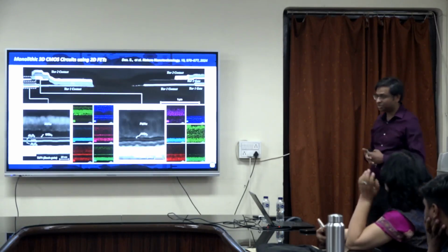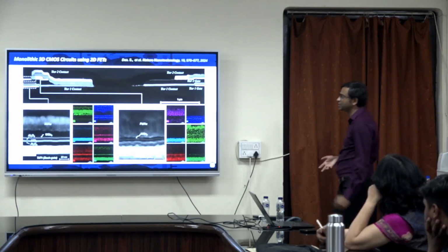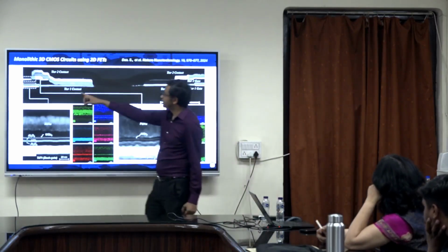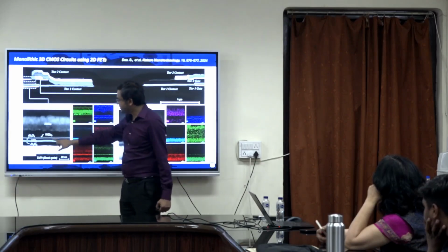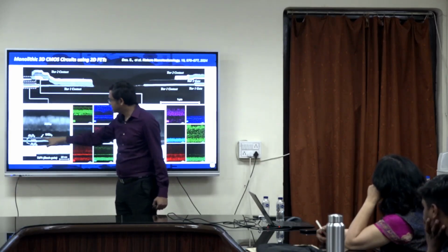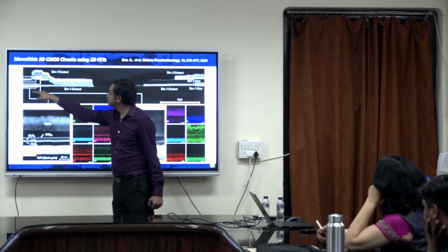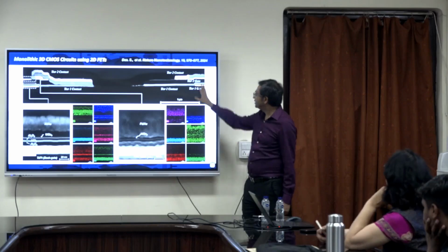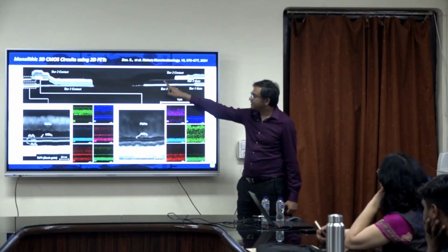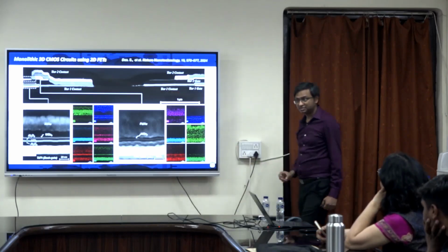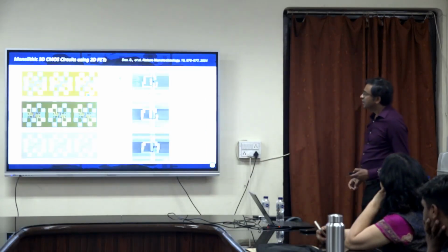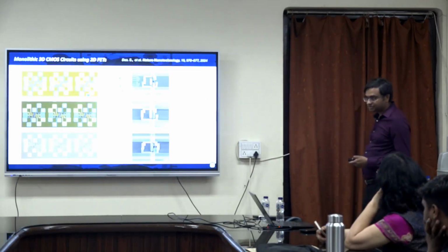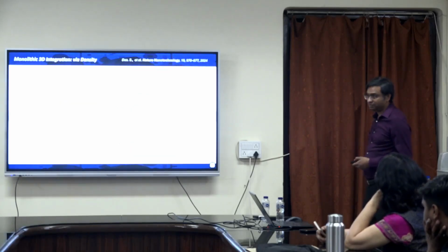Right, here is the cross sectional TEM. This is pretty wonderful looking. You see, this is my tier 2 tungsten selenide. Each device has this floating gate stack. Here is tungsten selenide bilayer, and then this is, I think, again tungsten selenide bilayer, right? And you can see the via connecting the 2 tiers of devices. Okay, and then we make all sorts of logic gates, inverter, NOR, NAND, and here is the comparison.